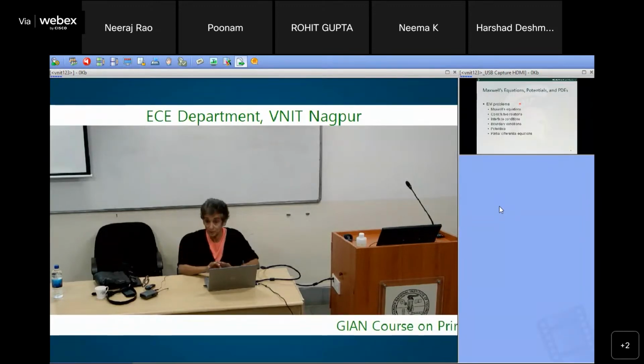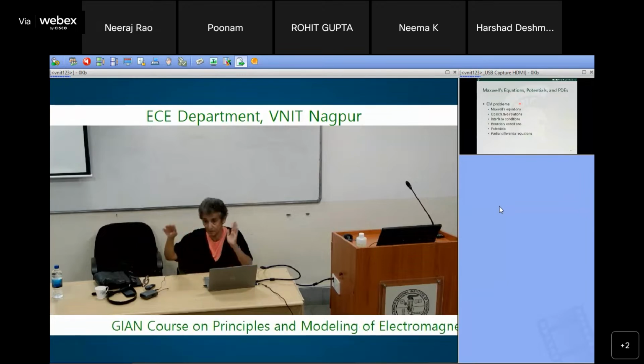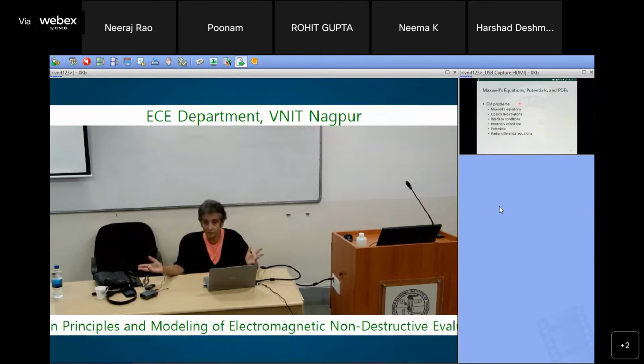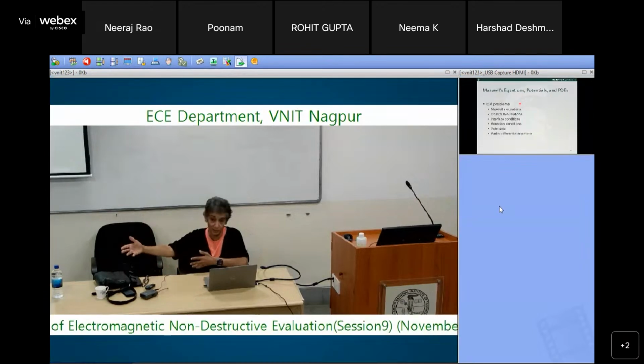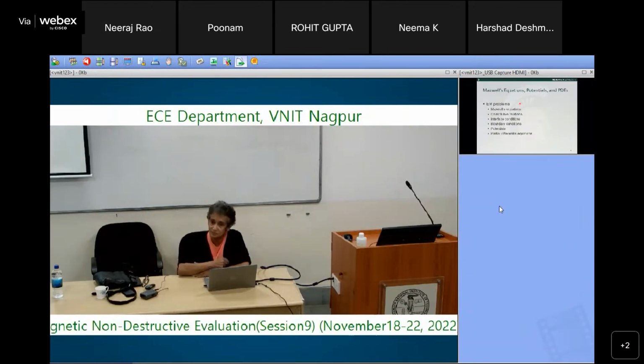At the input, you give the different signals, and in the output, you have the corresponding defect profile, and you let the neural network learn that mapping function. And then when you have a test signal, it will tell you what the defect profile is.